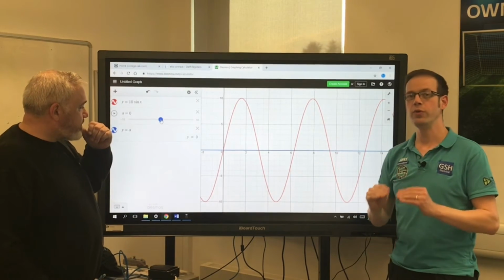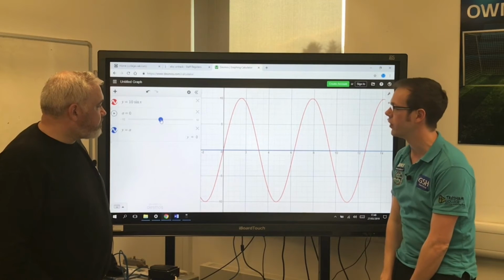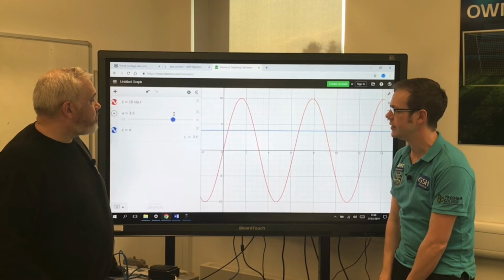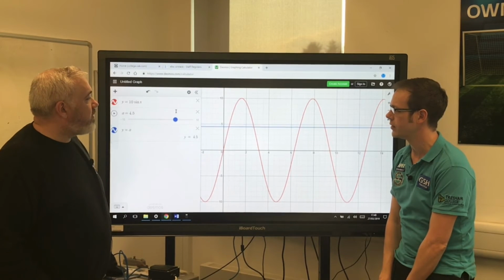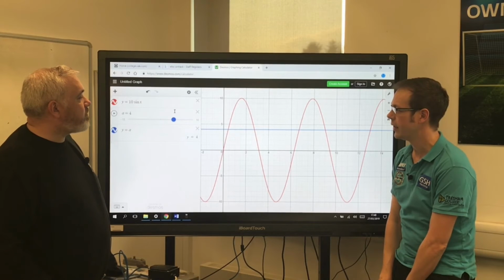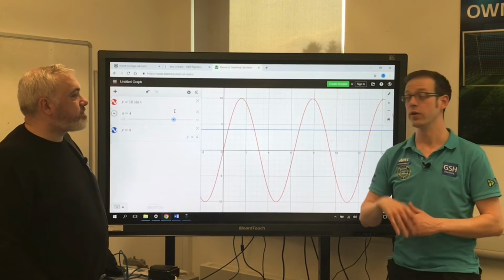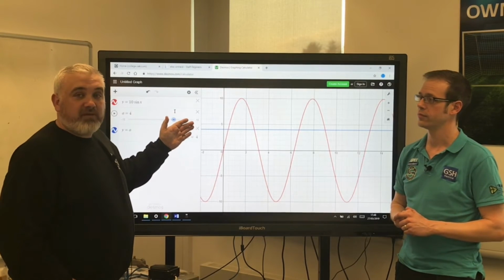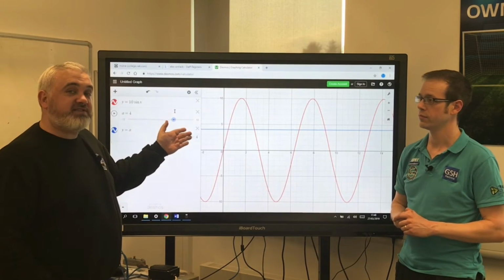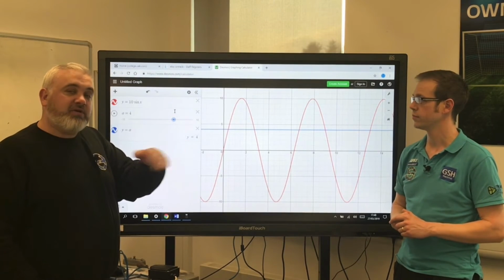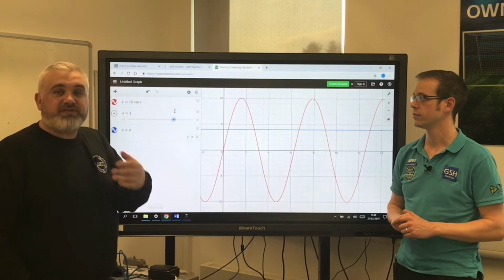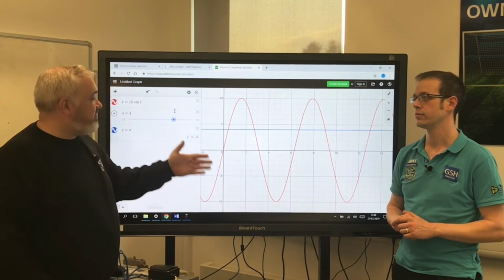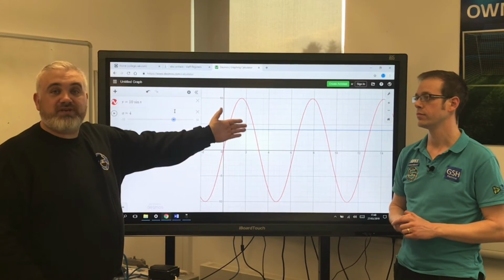Now a smooth DC waveform, as generated by some of the things that Paul mentioned earlier, looks something like this. So there's our DC waveform. That looks quite comfy, that sits quite happily there. It's just, in theory, a straight line. Now obviously we do get other types of DC. We do indeed. So that straight line could be directly from a leaking battery, a UPS, a PV system that's generating a smooth DC output. Stuff like TVs, washing machines, they use switch mode power supplies, rectifiers, which chop the DC. But for this example, it's just constant, smooth DC current.